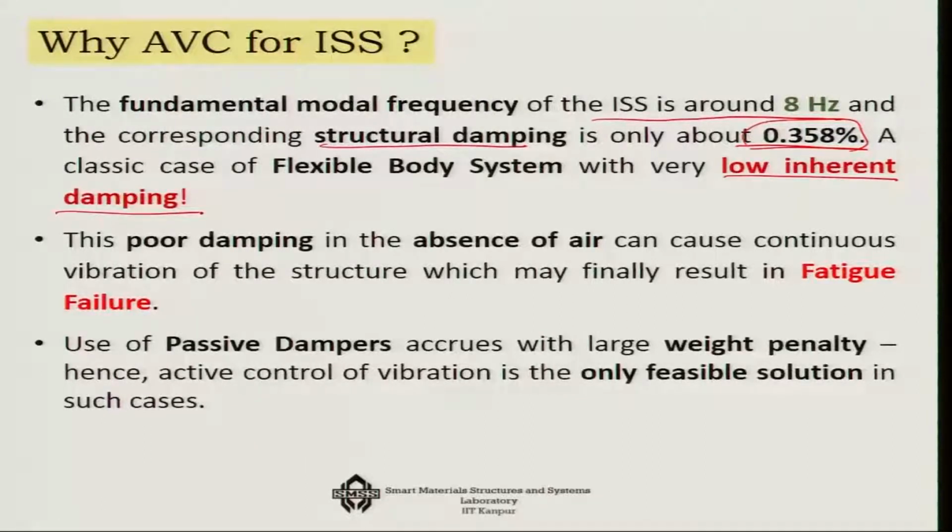So, in the absence of air, because there is no resistance, this poor damping can easily result in fatigue failure in the system. Now, if you try to use passive dampers, there will be a large weight penalty. Also, there are issues like in such a low frequency, not many passive dampers will be able to work properly. So, active vibration control is the only feasible solution in such cases.